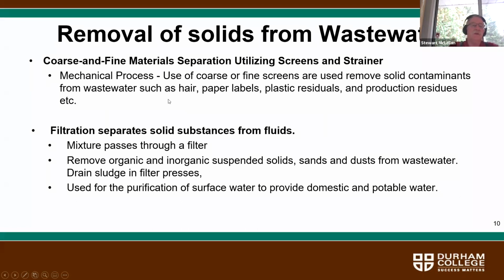So if you ever go into either a municipal or an industrial wastewater treatment plant, one of the first things you will see in there is generally some type of screen, and the incoming water is passed through that screen, and any coarse materials in the wastewater will be removed, because you don't want coarse particles like hair and paper, plastic residues moving through your system.